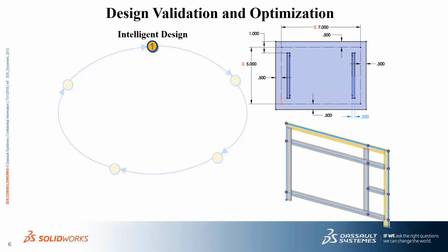In intelligent design, we'll take a look at creating a cabinet face using weldments and talk about the benefits of weldment profiles. We'll also look at using equations to drive changes in the size of our drawer models. I'll walk us through the weldments as well as finishing the cabinet with more common SOLIDWORKS capabilities. Then I'll show what we'll call a template part, or a blank part, that I can then change and save out for use in other designs. While I'm in SOLIDWORKS, keep an eye out for how seamless and streamlined these operations are.